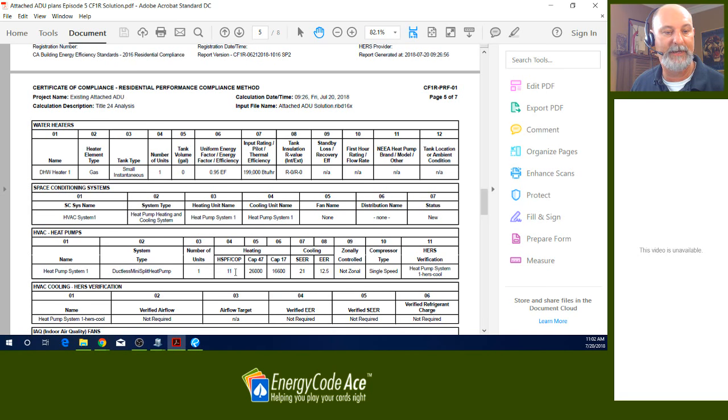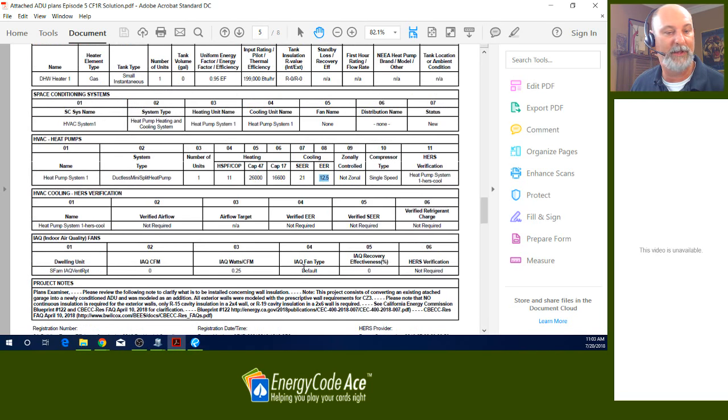Here's our heating efficiency, our cooling efficiency. This should match what the specs are, but just understand that the software is devaluing that cooling system automatically behind the scenes. You don't have to tell the software the 14 SEER and 11.70 EER. Just model it the way the specs are and move on. So good, and it's showing that we'd have 0 indoor quality requirements here.